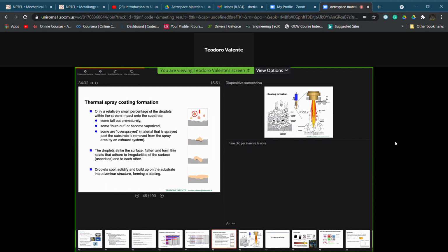Then, what is going to happen? The powders are melted. You have to think of a stream of powders which are projected by the flame. And so we have powders which impinge on the substrate and allow us to fabricate the coatings. But we also have powders which can in part undergo vaporization, because powders do have a granulometry distribution.